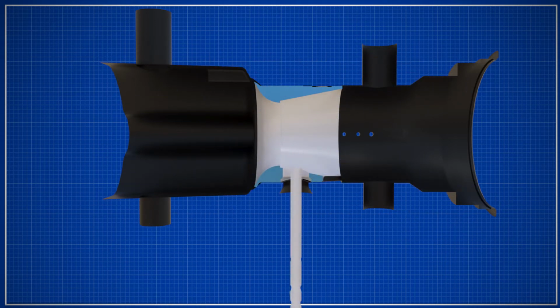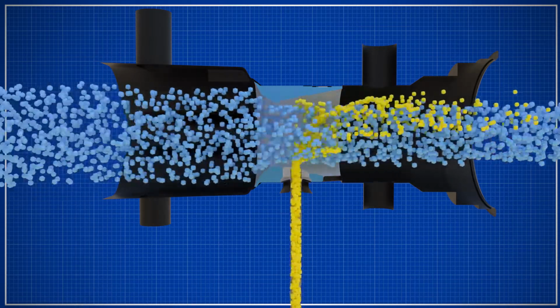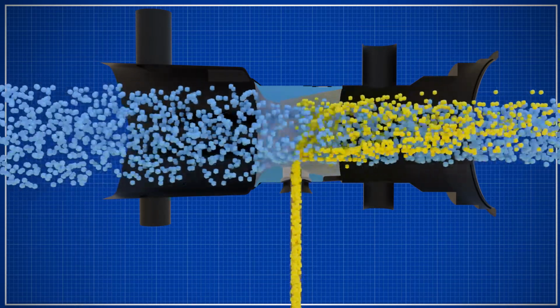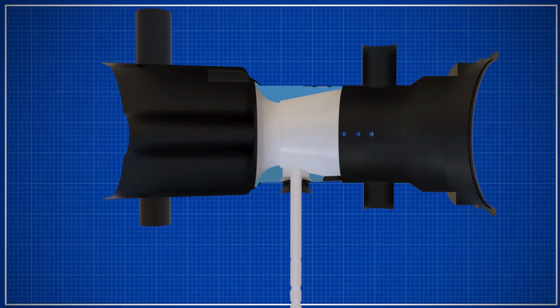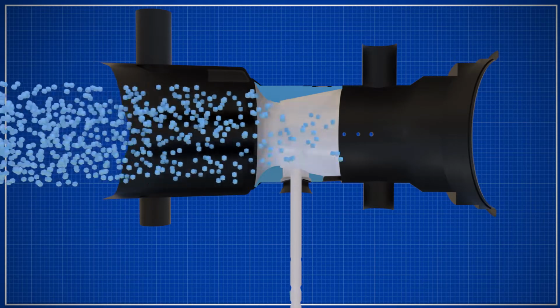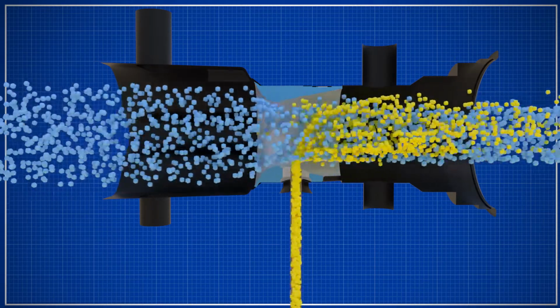If you put a tube in the venturi, you can leverage the lower pressure to move fuel into the air stream. This is the same as if you were to use compressed air across a straw and put it in fluid. The result is fluid movement and atomization of that fluid.